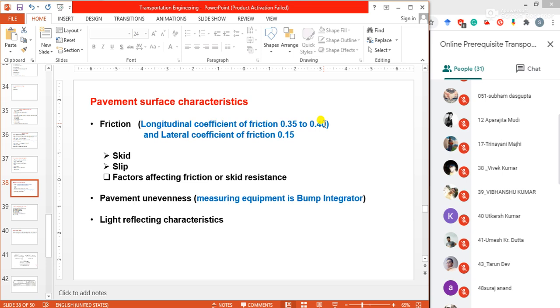In the case of horizontal curve design, the Indian Road Congress has recommended the lateral coefficient of friction 0.15. This low value of transverse skid resistance has been suggested considering the worst possible surface conditions, such as mud on pavement surface at horizontal curve with super elevation during the rains, as it is essential to prevent possible lateral skid even under adverse pavement conditions.